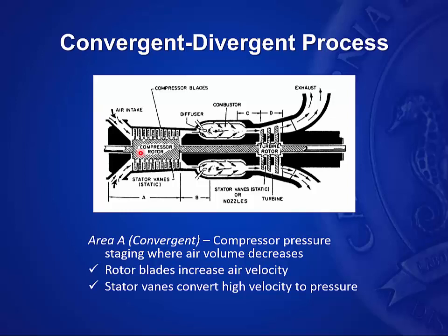The one thing to talk about these rotor blades or vanes is the rotor blades themselves are an airfoil shape. So similar to what we were talking about on the steam turbines, these have a definite airfoil shape, and they have a corresponding optimal angle of attack with the air striking the front of those blades. But anyway, from the inlet vanes, then you have your compressor rotor blades, and then progressively you have a stator